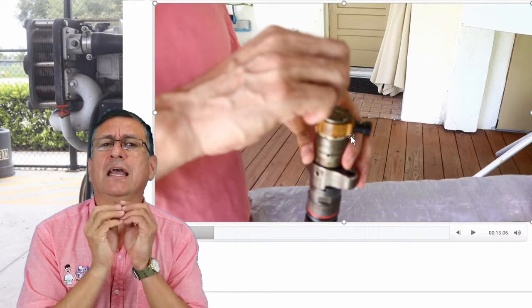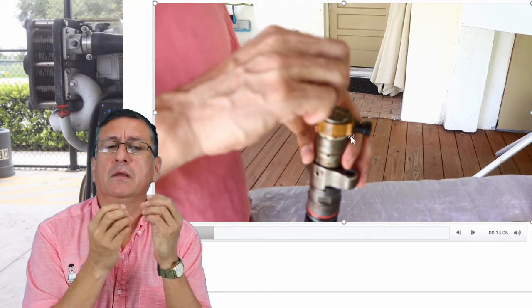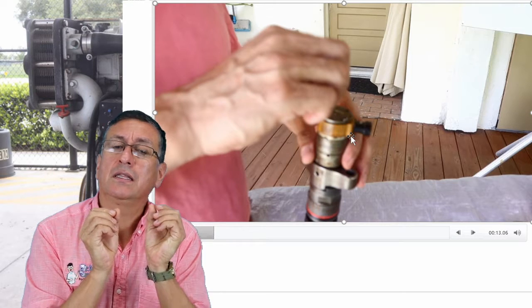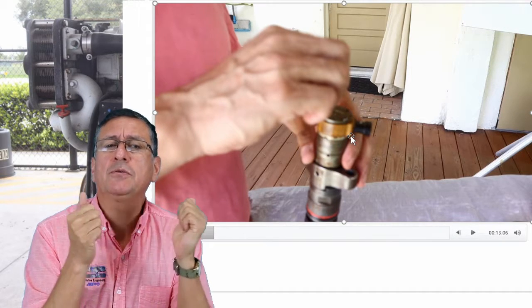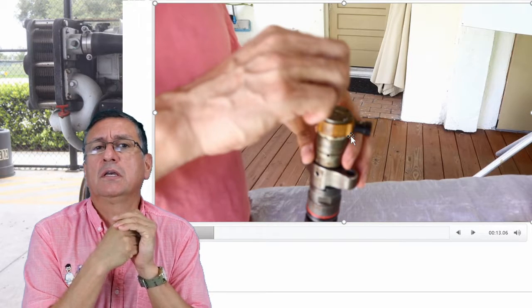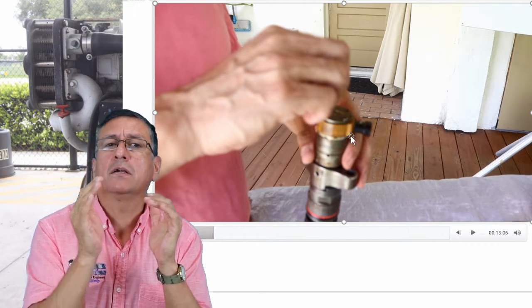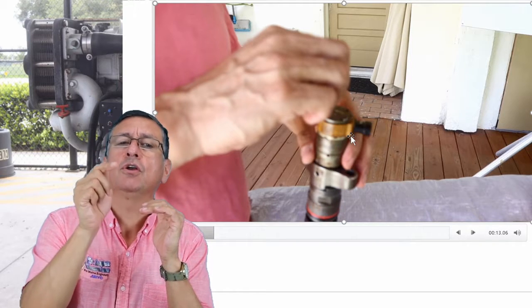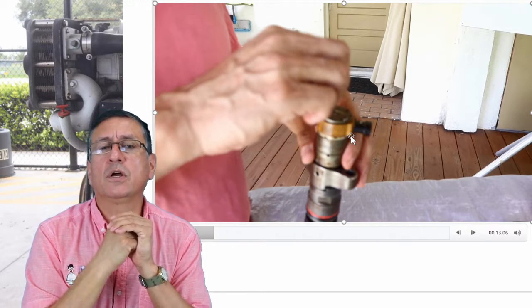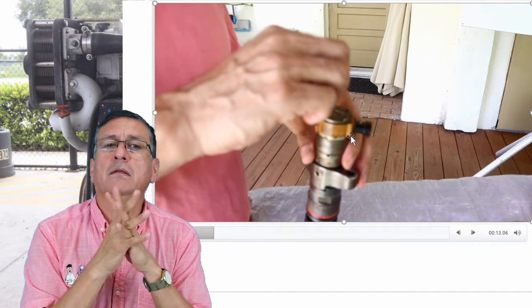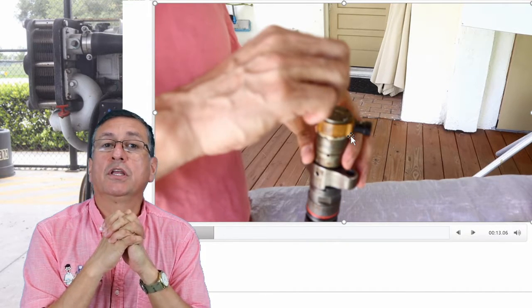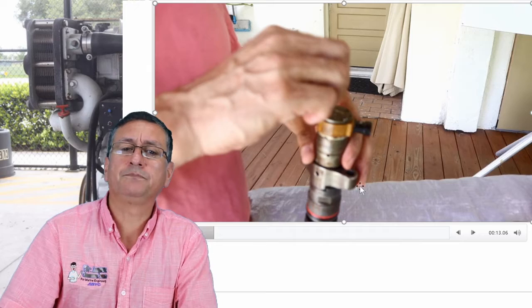Yes, my friend, if you have the part number of that injector, you can order the solenoid. The solenoid is coming with the spring and the washer. Remember that the elements that produce the pressure, you remember in the previous one, are the spring, the pin, and the washer. Those elements produce the pressure. If the injector is not working under the operational pressure, you replace those elements, spring, washer, and pin, and immediately you recover the pressure on the injector. Of course, if the fuel is coming with the appropriate pressure. Right, this is the process.